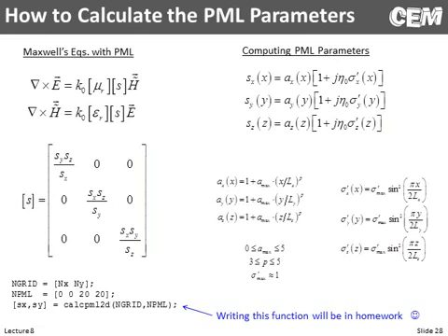So it turns out there's a whole science to this, and what I'm showing on this slide is one very good way of calculating these PML parameters. The important thing to realize is that we don't want to go from our problem space immediately into a big PML with big numbers introducing lots of loss. So we tend to taper into it. That first cell in the PML will only have a little tiny bit of loss. And then the next cell is going to have a bit more, the next cell is going to have a bit more, until finally by the end of the PML, at the very edges of the grid, we're going to have a lot of loss. And so that tends to work very well.